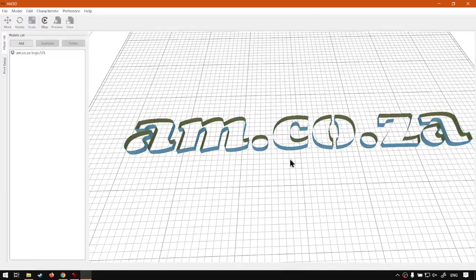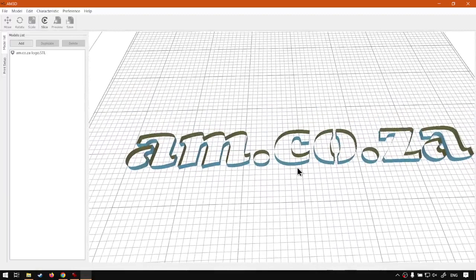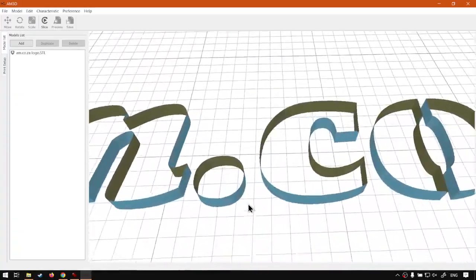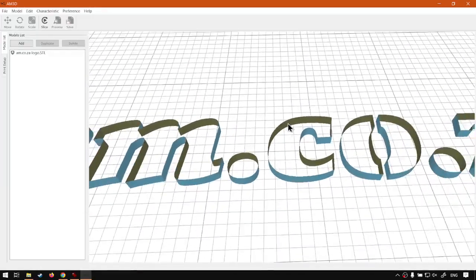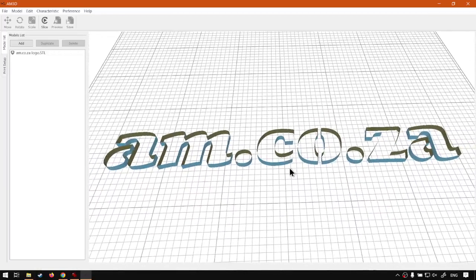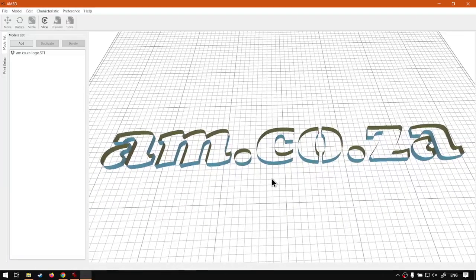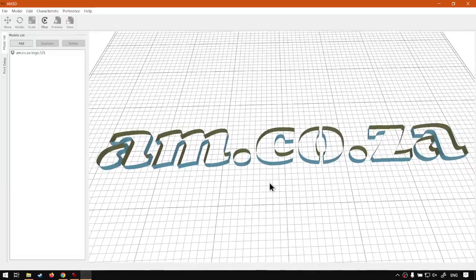So in any case, it can be selected, keep your control in and left mouse button, then you can pan. Then for zoom, we want to keep our Alt key in on the keyboard, click and drag forward to zoom in and backwards to zoom out. So this, like I said, you can see is way smoother zooming. I sometimes prefer that to the mouse wheel, but you know, sometimes I use both depending on what is required. If I'm really close, I might use the Alt plus left mouse button to get a fine control. Where I'm far out, I might use the mouse wheel to quickly get close.